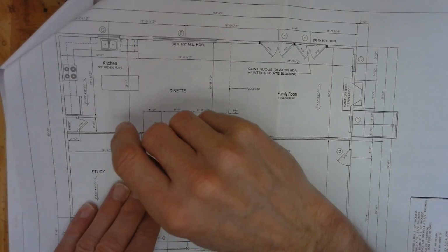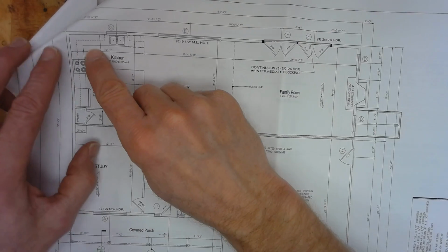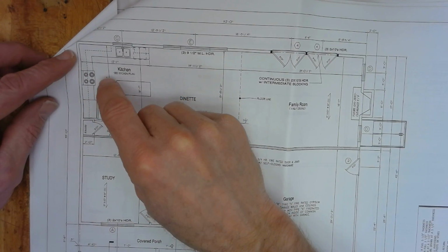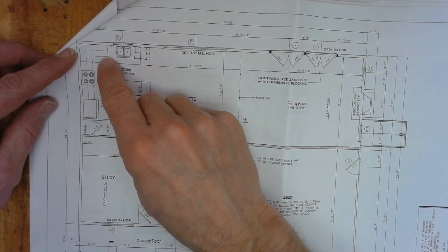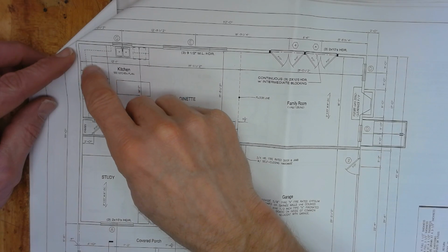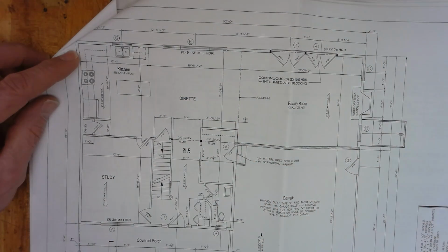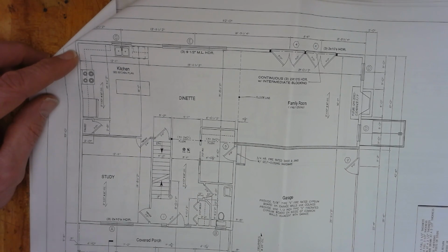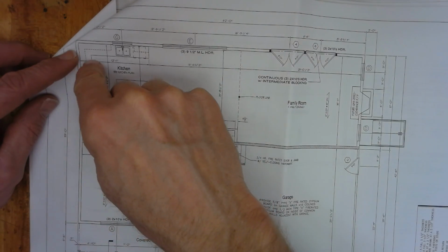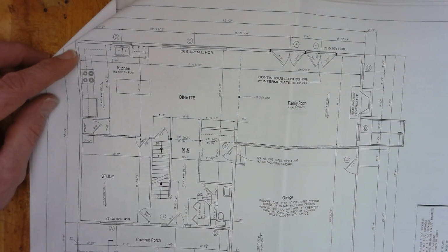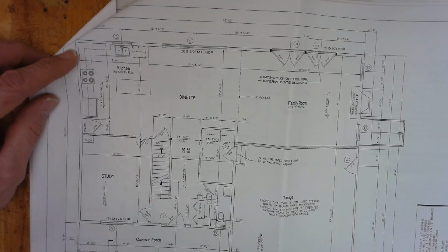I'm going to give you one more example here in the kitchen. Right? We're looking down from about maybe belly height, so we'd see the kitchen countertop here. This is the countertop, but look at this dotted line. This dotted line right here represents the kitchen cabinets, the overhead cabinets that are really above your belly. They're really above your head. We want to show them, but we're really not seeing them when we look straight down. So we show them with what we call a hidden line, because you really don't see them in this view.